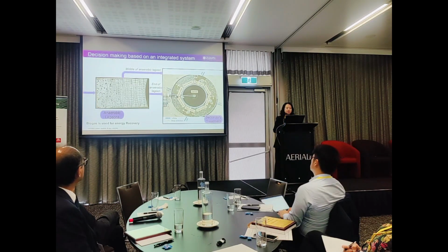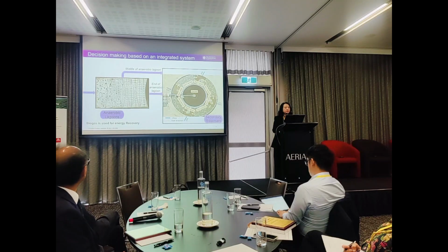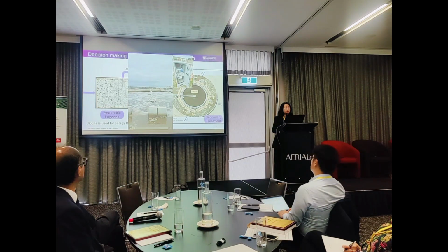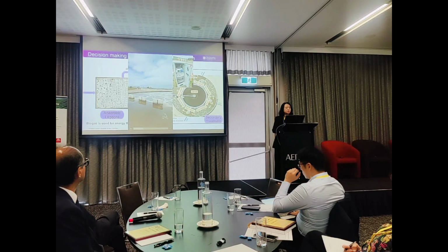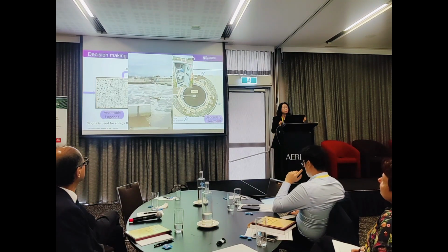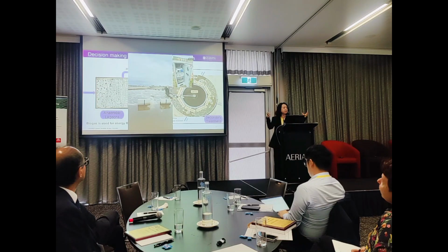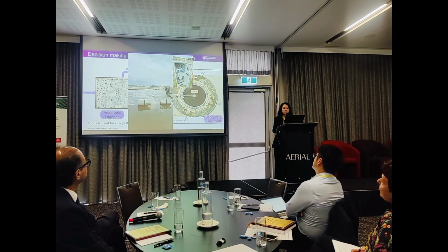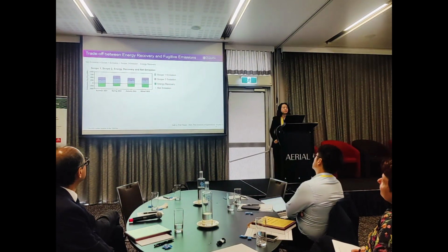What we are doing is trying to capture all the greenhouse gas emissions in this treatment plant during the nitrogen removal process. This is quite small. These little dots you can see are the hoods we put on. I do have a video. This is the treatment plant, from the anoxic zone to the aerobic zones, and in the aerobic zones we capture the off gas using floating hoods. Those gases are sent to a centralized analyzer, so we can capture all this off gas, methane and N2O, online.